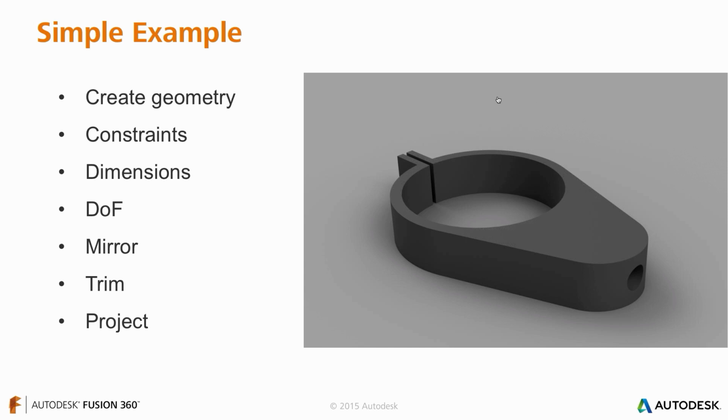In addition to geometry, we have constraints, and you can think about constraints as simply rules that are applied that really relate the geometry to each other inside of a sketch. Constraint examples might be parallel, coincident, concentric, pretty much rules that define how certain sketch geometry can move and how it cannot move. And then lastly, we have dimensions, which really just set the sizing of sketch elements. This might be how large is your circle, how far apart are two circles, how long is your line, what is the angle, those sorts of things.